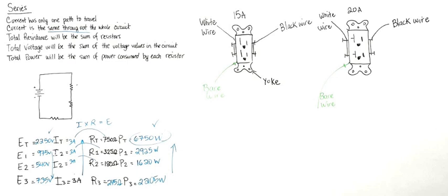You wanna use the formula that works so that you can get other values, so that you can continue to solve for the circuit. So this formula tells me that if I want I, and I only have power and voltage, what do I need to do with them? Power divided by voltage, right?